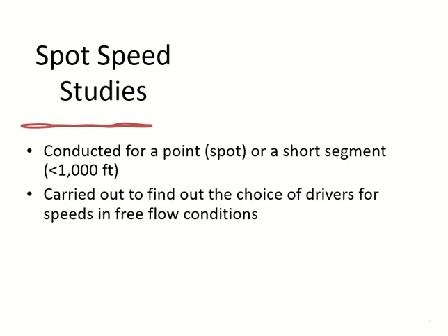Why do we do spot speed studies? Spot speed studies are done to find out the choice of drivers regarding the speed on the road, what speed the drivers want to drive at on the road. And this can only happen when you have free flow conditions.